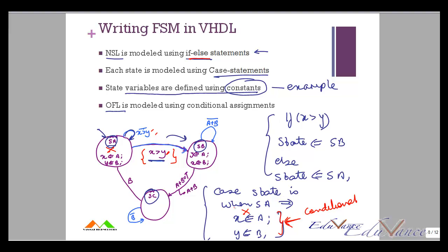For example, case state is when SA or when SB or when SC, if you remember the case statement. Now the output function logic, or what happens inside each state, is defined using conditional statements. If there are no conditions, you will have direct assignments.